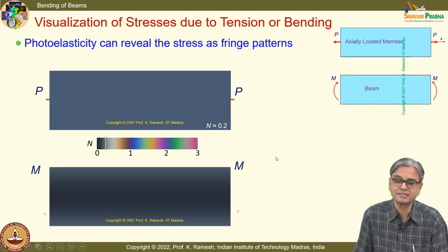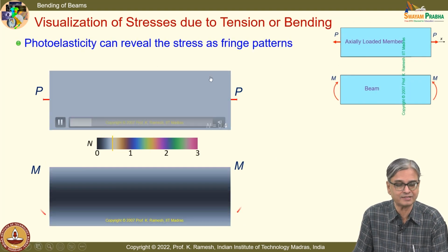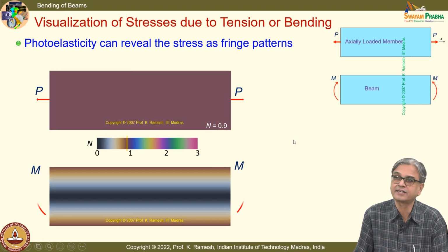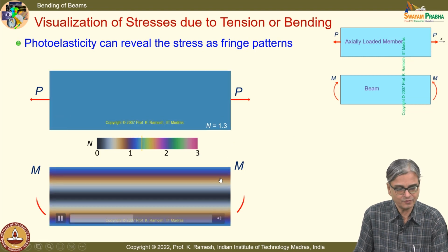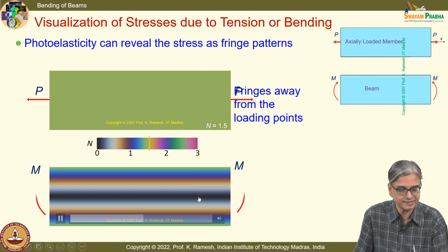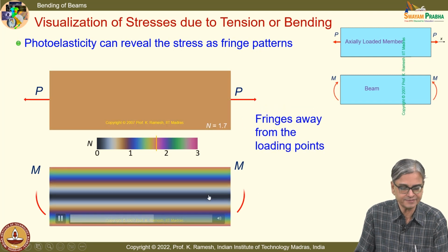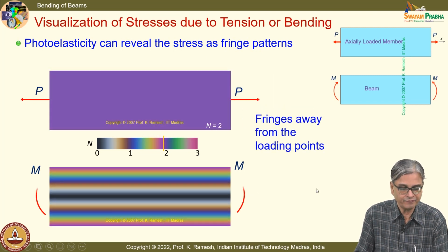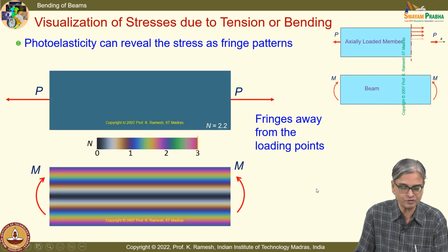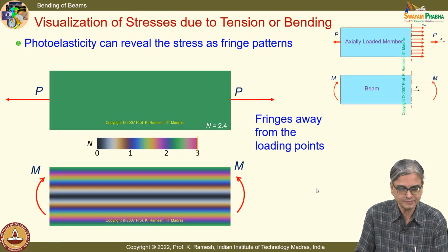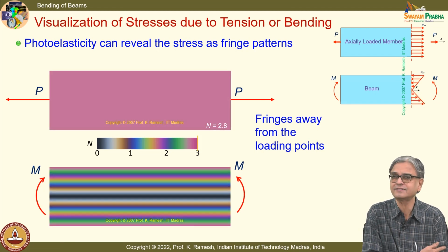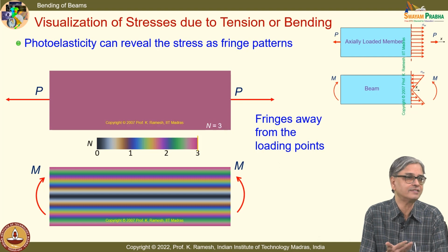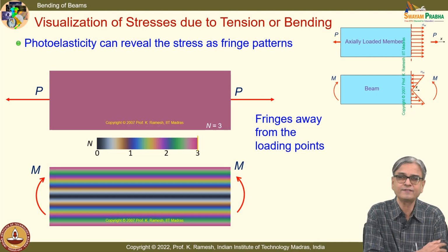When we started this course, we started with photoelastic fringe patterns, where I have this as constant color for an axial load. For bending, you have this as densely packed lines, and we found that the distance between the fringes remains constant for a particular load. And now we also go back, we have learned what is known as a neutral axis. Can you identify neutral axis in photoelastic fringe pattern? What is a neutral axis?